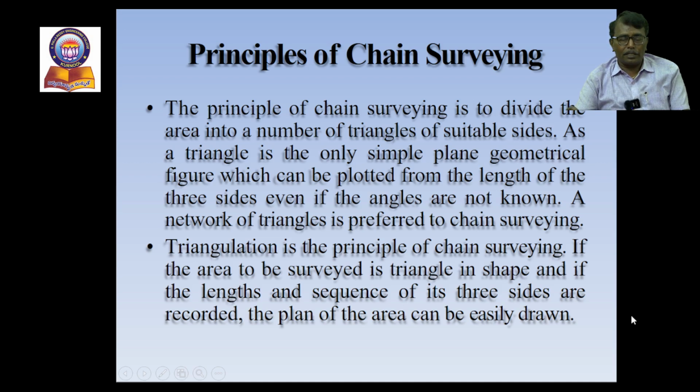So the next is the principle of chain surveying. The principle of chain surveying is to divide the area into a number of triangles of suitable sides, as a triangle is the only simple plane geometrical figure which can be plotted from the lengths of the three sides, even if the angles are not known. A network of triangles is preferred in chain surveying. Triangulation is the principle of chain surveying.